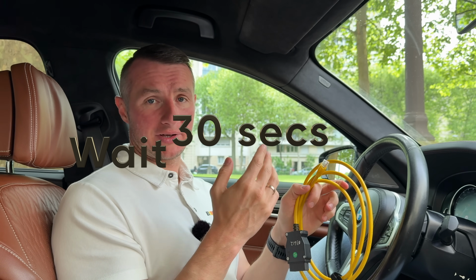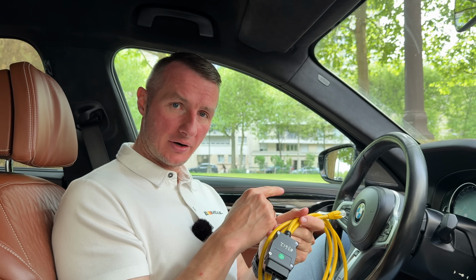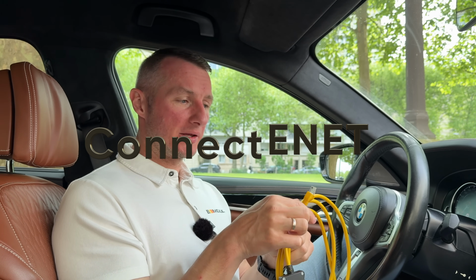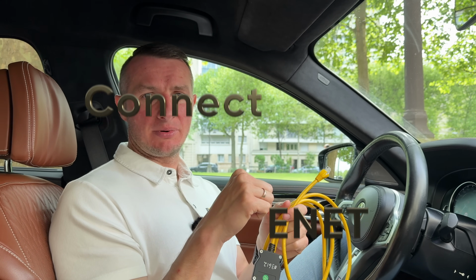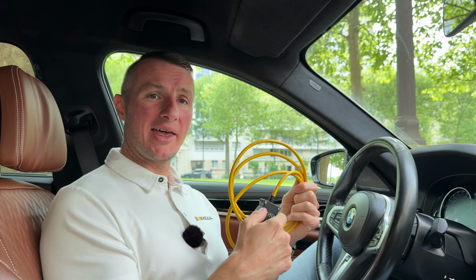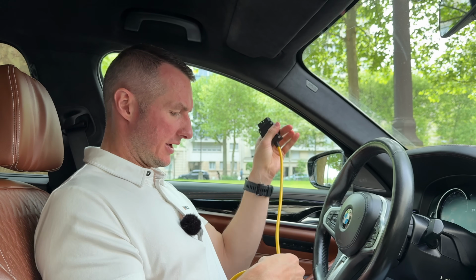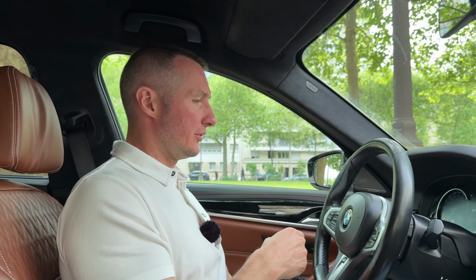Then, when the engine has been running for at least 30 seconds, you will connect the ENET cable to the car. And only then you will connect the ENET cable to the laptop. This is required for all the ECUs, more specifically for the gateway ECU, to boot up properly and set up all its internal things correctly. If you do it in the reverse order, you might not establish the connection with the ENET cable. I'm connecting the car and loading up the computer.